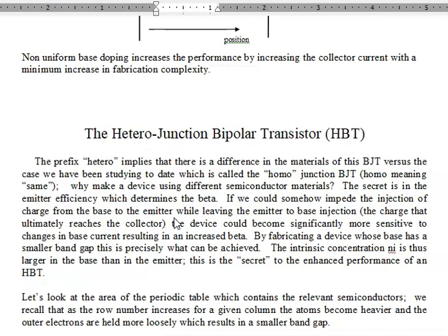And you recall that for the normal device, the homojunction BJT, if we put 6 volts bias on the emitter base junction, we have a boost of 10 to the 10th, and that boost is for PNP, for holes injected from the emitter into the base, as it is for electrons injected from the base into the emitter.